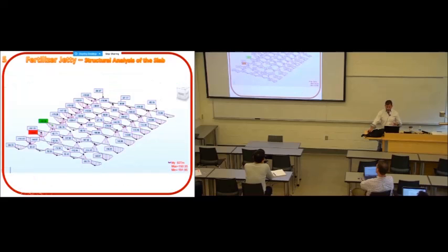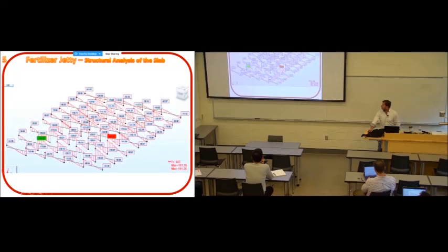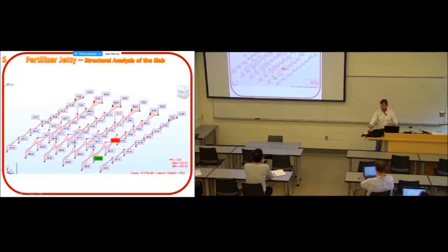And by doing so, you get the moment diagrams for a section that is 22 meters long, because this is a 440-meter-long jetty, but it's easier to divide it into 22 meters, because every 22 meters we have one bollard. So it's repetitive. You analyze it in 3D, but it's modular 3D. So this is the moment diagram in the Y direction and the X direction, shear diagram, and in the other direction, shear diagram.